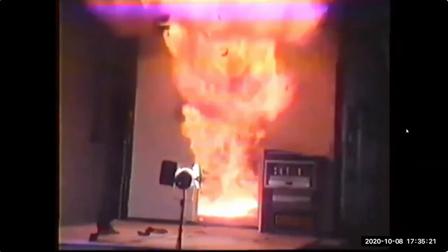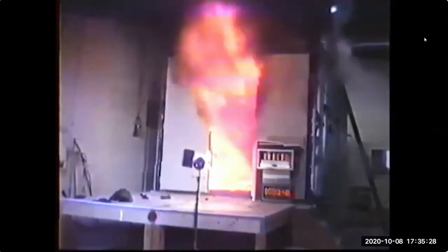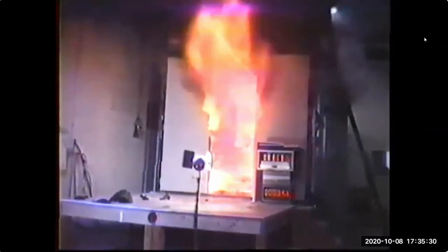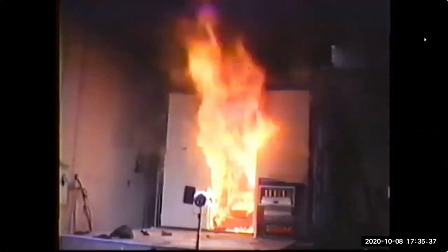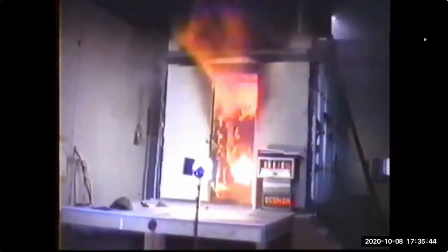interior finish, as far as its form factor and material properties, has a powerful influence on flashover. And in this case, this is craft paper. The craft paper being that facing for insulation you frequently see in rooms that people have started to do construction on and haven't bothered to put the gypsum up to protect it. So you can expect a very fast reaction here. And it's not a lot of mass. It's very limited mass. It doesn't take much for this kind of an event to occur. So just keep that in mind.